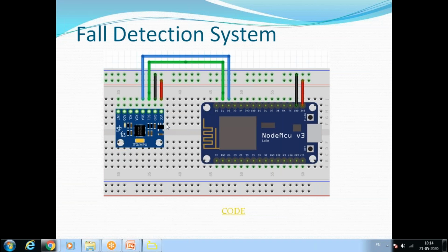So why is it called a slave? Because without the master, it can do nothing. But the master is independent. When we use, say, the RS232 protocol, it is asynchronous. That means both the transmitter and receiver have their own clock source.